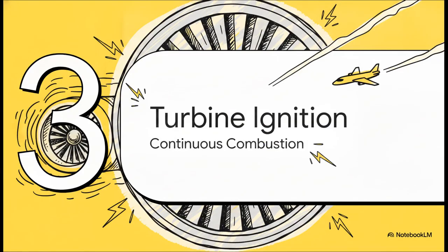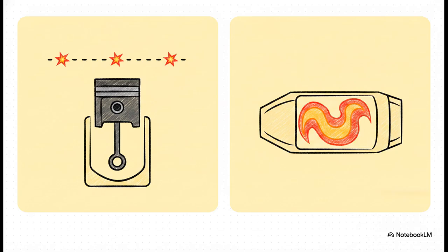All right, get ready because here is the level up moment of the course. Module 3, Turbine Engine Ignition Systems. We are stepping boldly into the jet age here. And the biggest mental shift you've got to make is understanding the duty cycle. Reciprocating engines, like we just talked about, require an intermittent, perfectly timed spark for every single compression stroke, over and over again.